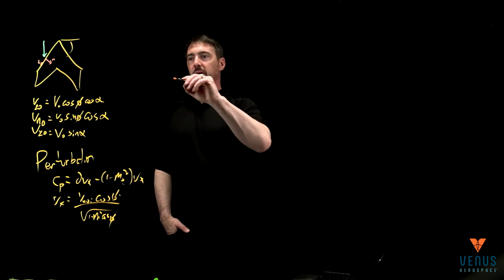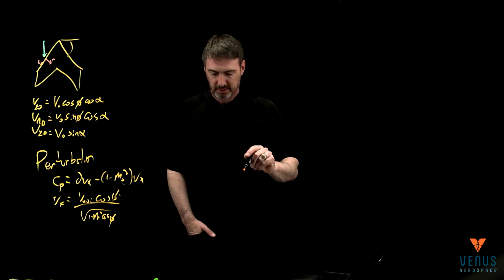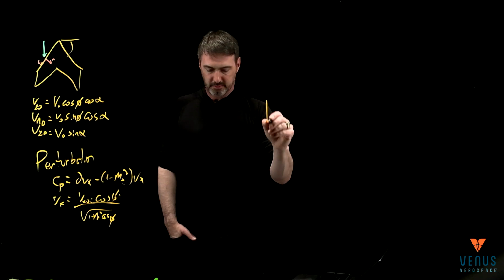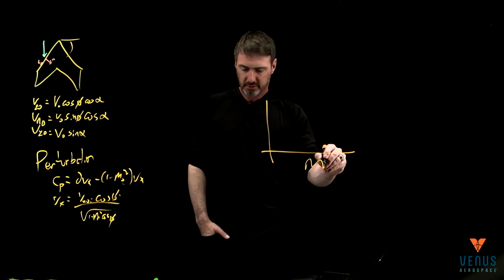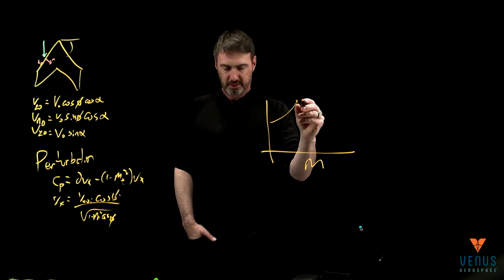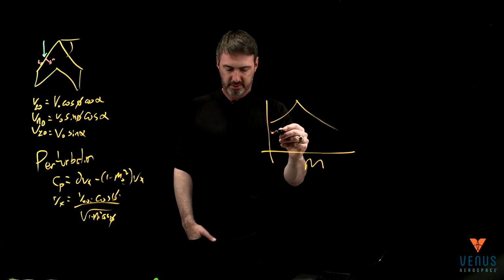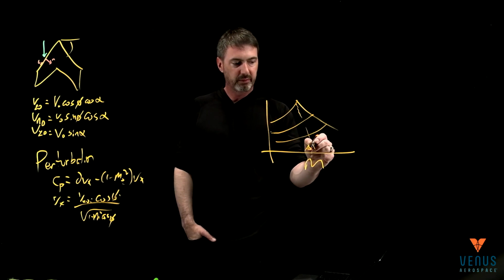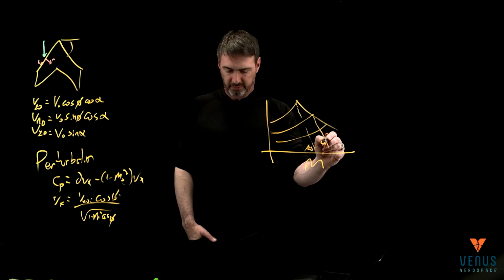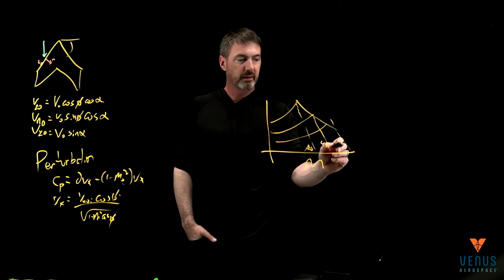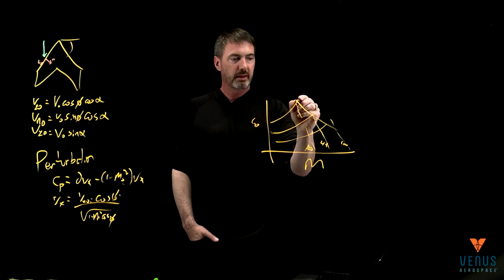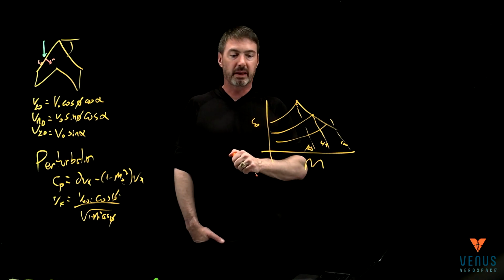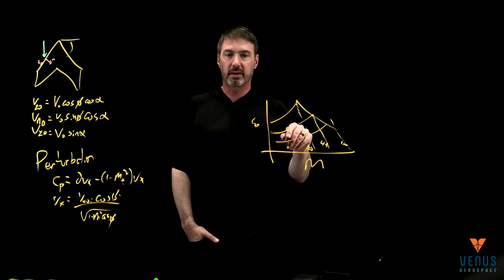And so, with a whole bunch more math, a couple of interesting graphs show up. I'll draw it over here. This is Mach number, and you end up having a delay. This is for phi equals 0, this is 45, 60, and this is CP. If this is the critical Mach number, where the drag is spiking up, you see it's delaying that onrush.